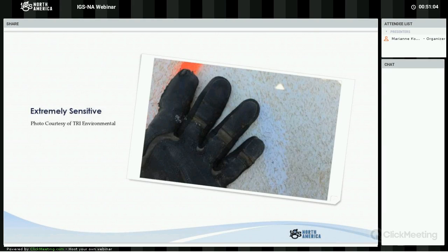So the conductive back geomembrane product, if you don't install it in such a way to isolate those fusion welded seams, you can't test all the way up to the seam. You have to stay about, see, the ASTM says 100 millimeters away from the seam. So a method of installing this conductive back product in order to enable other leak location methods and in order to avoid the false positives on the overlap is something that we finally gave a definition to this past year.